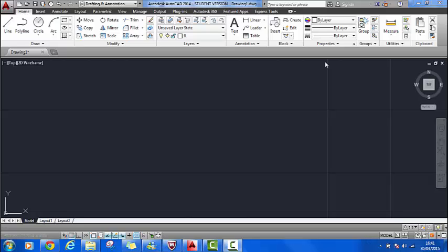In this video we're going to explore the basic elements of the line command, which you can find up here in the draw ribbon. It's the very first command. Lines can be created using polar coordinates. Now, what are polar coordinates? Polar coordinates use distances and angles to describe the position of a point. The distance and angle are made relative to the origin, the 0, 0.